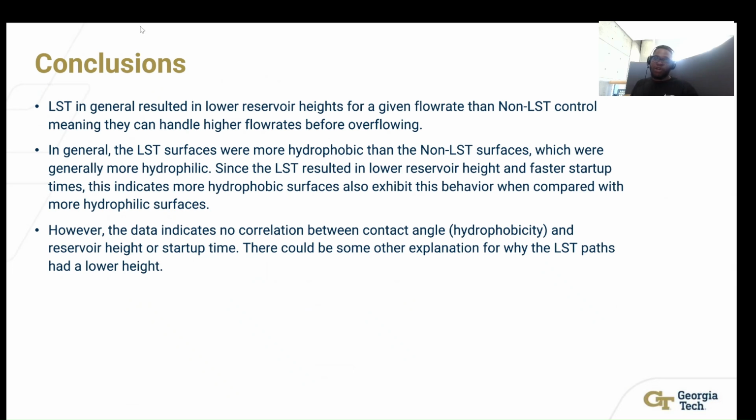So we made a few conclusions based on a test that we did run. We determined that the LST in general resulted in lower reservoir heights, which I just mentioned, for any given flow rate compared to the non-LST sample. So the LST samples can handle much higher flow rates before overflowing. These flow rates would indicate, depending on the severity of a storm that was coming down, for example.